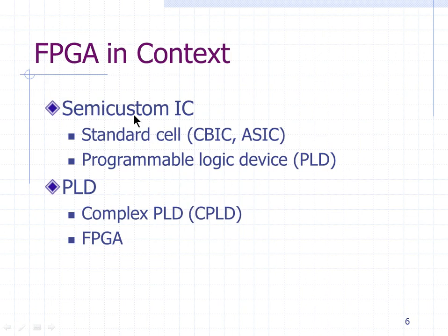Then you have something called semi-custom IC design or semi-custom ASIC design. They are using standard cells, meaning standard libraries. Libraries are given to you. So the designer doesn't work at CMOS transistor level, rather the designer works at a library cell level. So cells or components of the libraries are used to build your design. And then traditionally PLD was part of semi-custom, but PLD is a new category for a while now.